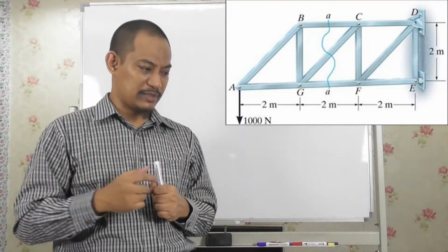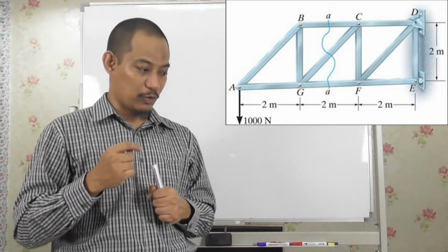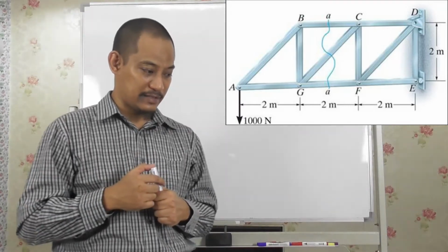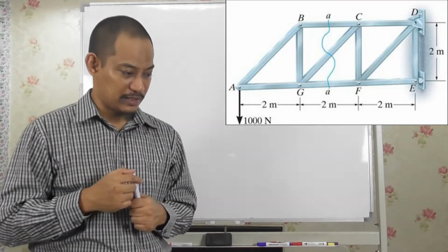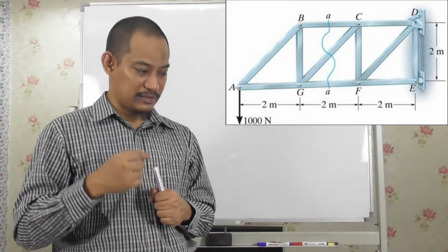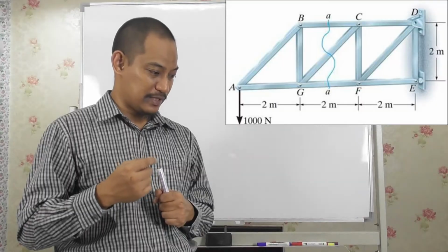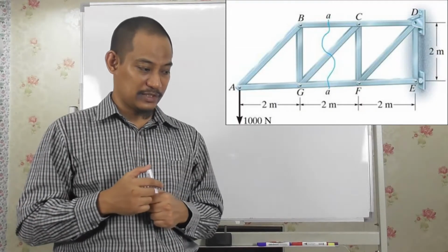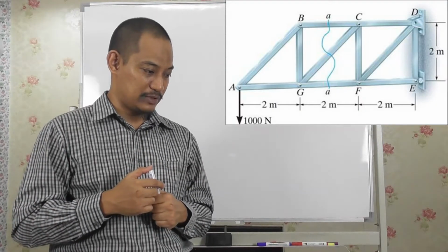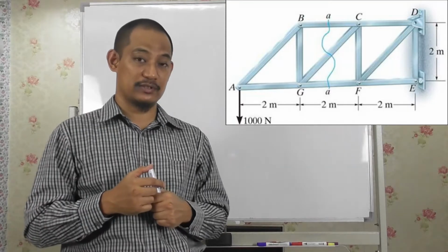Since truss members are subjected to only tensile or compressive force along their length, the internal force at the cut member will also be either tensile or compressive, with the same magnitude as the forces at the joint. This result is based on the equilibrium principle and Newton's third law.